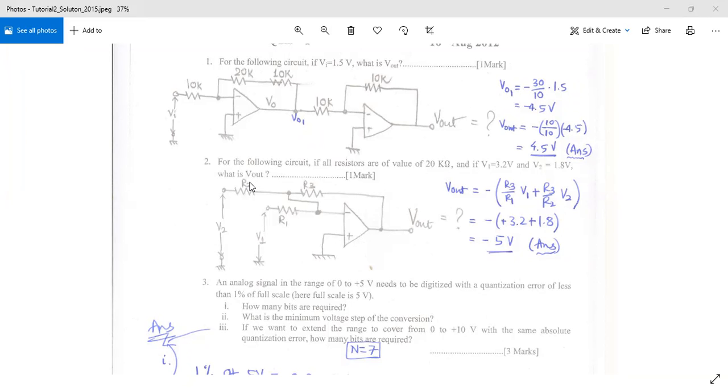So just considering this particular circuit that we are given, you can see these two particular branches are in parallel. In an inverting amplifier, this particular node has a virtual ground. So these two nodes are connected, and whatever voltage we have at this particular node is the same voltage at this particular node as well. So this is also virtually grounded.